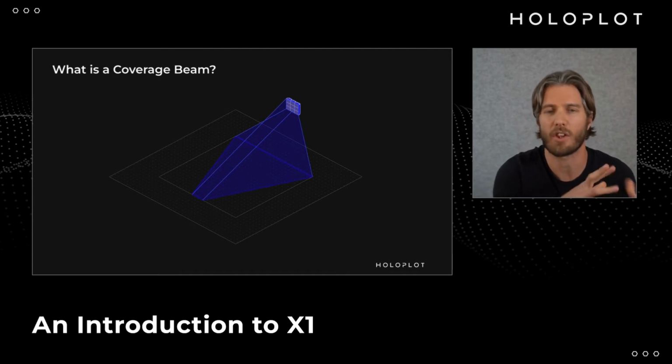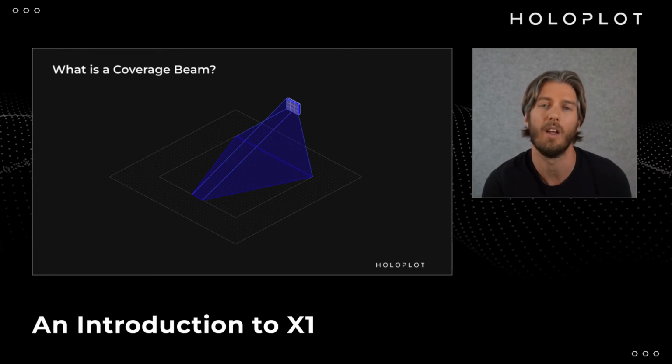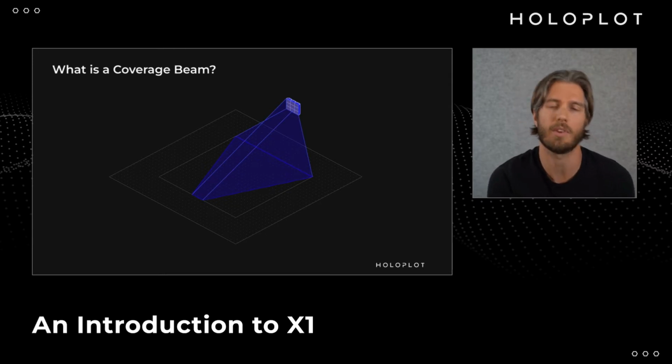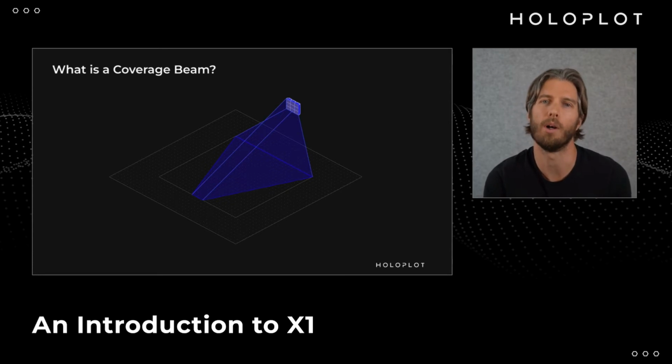You get none of this hot spotting that you would off a point source when you're very, very close to the sound. You really reduce that down. And this means that every audience member gets the same experience. In terms of how many of these beams we can create per array, we said that it was 8 with the parametric beams, and for the coverage beams, because they require this level of pre-processing, we can create 4 of these coverage zones per array or per module.